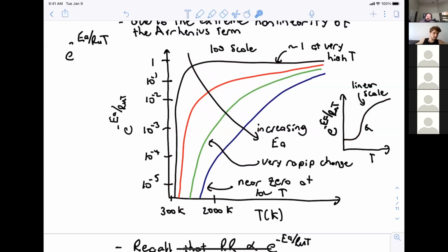And so what we'll be doing on Wednesday is deriving Semenov theory for thermal explosions, which results in an ordinary differential equation in the transient form, and an algebraic equation that needs to be solved, a fairly easy one, in the steady state. And then you can apply those to a given energetic material and decide whether it's going to blow up under a condition or not. Okay, and so that's it for the lecture today.